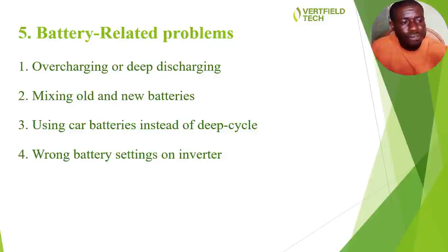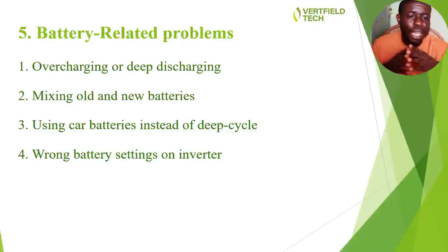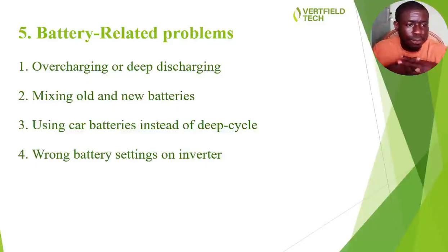But if you are using a fake charge controller or a fake inverter system to charge your batteries, then when the solar charge controllers or solar inverters are expected to cut off energy from getting into the battery, they continue to charge them. That means your batteries are going to be overcharged. Overcharging of a battery can actually damage your batteries. When you see your battery swelling up, it is an issue of overcharging.